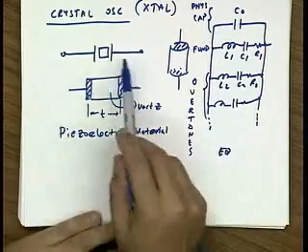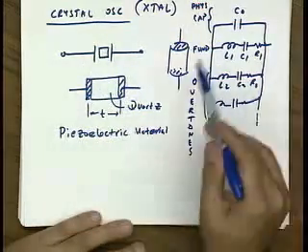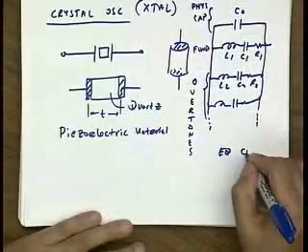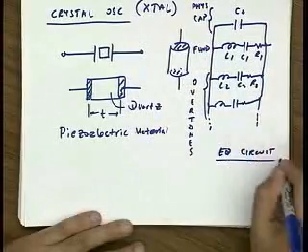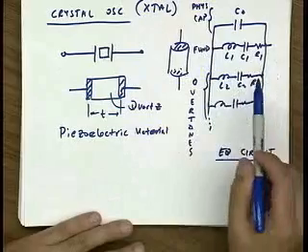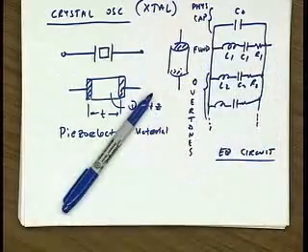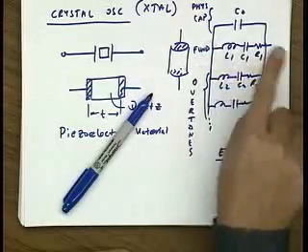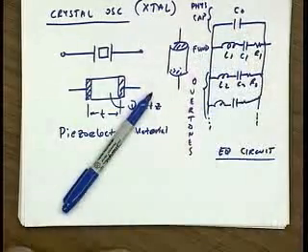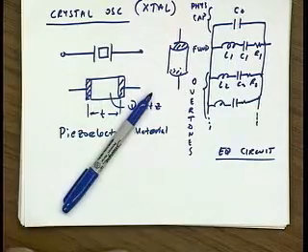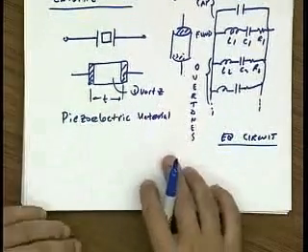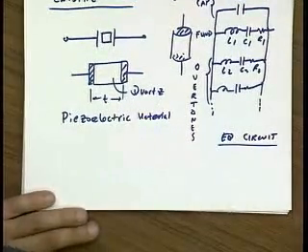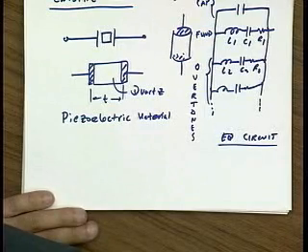Anytime you see something like this, you can put in an equivalent circuit like this. And if you know what you're doing, if you're only concerned with one particular mode, and you've taken precautions to suppress the other modes of the circuit, you can just use a simple series LCR with that capacitor to model it. Okay. Now, question? Where's the C0 from again?